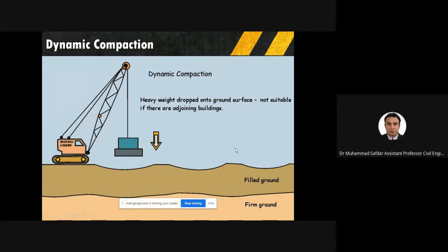Please continue. Yes. Dynamic compaction. It is actually an effective, efficient, and cost-effective soil improvement technique that uses the dynamic effect of high energy impacts to densify weak soil.